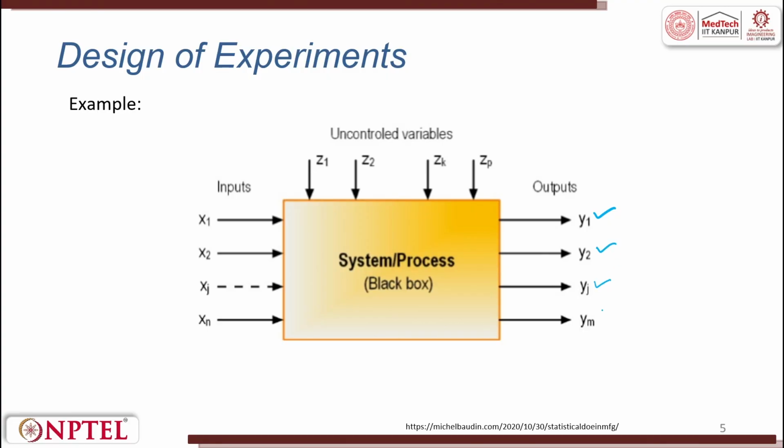Or maybe we will say where in the turbine blades there should be minimum 2-3 responses which can select. In the case of the machining itself, the response parameters could be quality and also the performance. Performance in a way, quality would be the surface roughness what we are getting. The performance would be what is the tool wear. Tool wear is to be minimized, surface roughness is to be put to a specific level. So, the way we design it depends. Those are all output parameters y1, y2 till ym varying from yj. These are the output parameters which we are working upon.